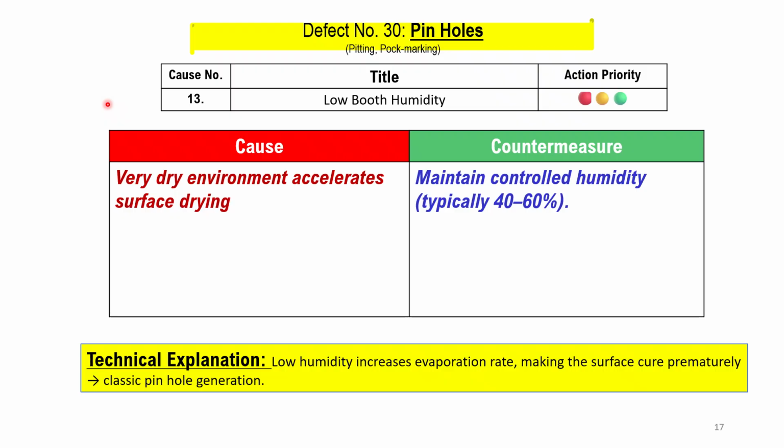The 13th cause could be low booth humidity. Very dry environmental conditions accelerate surface drying. Low humidity increases the evaporation rate, making the surface cure prematurely, resulting in classic pinhole generation. Therefore, maintain controlled humidity, typically 40 to 60%.